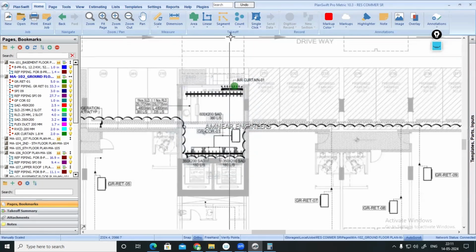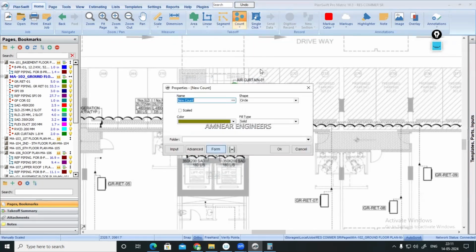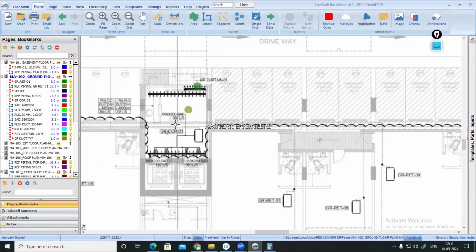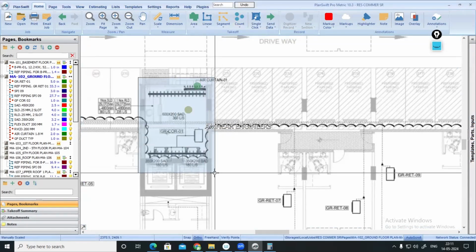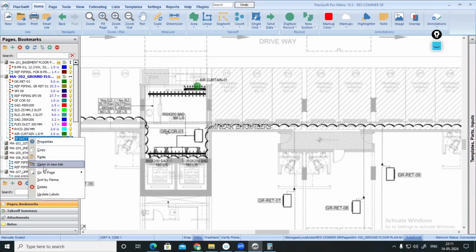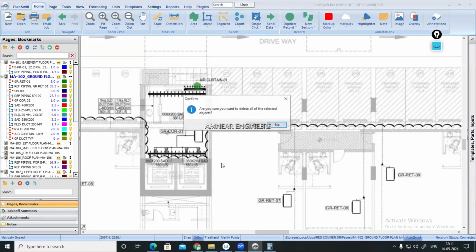Okay. So I'm just marking a note: ground floor duct typical one. Because when I am doing the estimation, I don't want to count that once again. Rather, the duct quantity that I have obtained in the ground floor, I can multiply by 2. But if there is any difference, you can't consider that as typical. Why? The problem is, if it was the same, then that is okay.